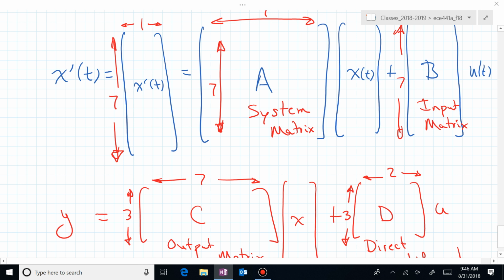So go back to your free body diagram. It's that long equation for M1 Z1 double prime. Solve that for Z1 double prime, which really means divide everything by the mass, M1, and isolate Z1 double prime on the left. And that's actually equal to X sub 2 prime. Then if you have a Z1, you replace it with X1. If you have a Z1 prime, you replace it with X2. You're trying to rewrite that equation in terms of how we've labeled the state variables and the inputs.